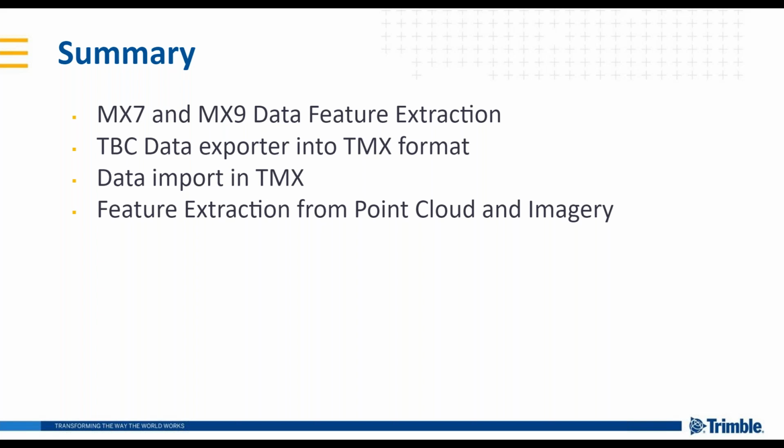This could be done either while creating the vector file itself, in any coordinate system with GeoEd or any height model that you like, or while exporting this data, in a different coordinate system with GeoEd as well. It's also worth mentioning that the geoid model is not defined by default in TMX, so the user needs to define this geoid model in the coordinate system of the software to be able to use it before creating a run or a vector file. Yeah, that's correct.